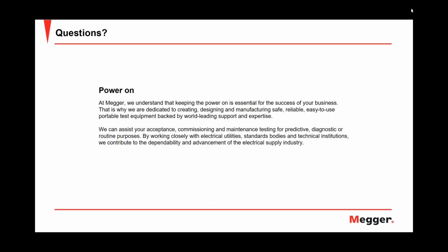Yeah, just to add to this a little bit, because one part of the question also asks about the breakdown. When you do the fault location, going back to the stepped sequence, you use DC, because cable fault location equipment doesn't have an AC source. The basic source to execute all the high voltage functions is your DC source, charging the cap, the burner and everything. So in this case, you only have DC available, and this is why you would do that step with DC. And you can see the difference when you do fault location. That's a whole different premise.